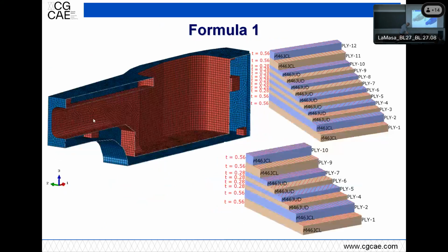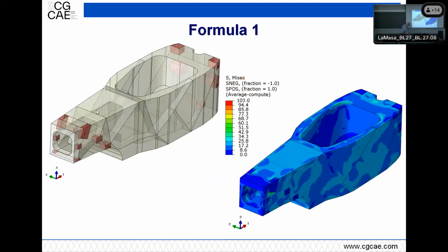And so I also tried a different approach. Following the suggestions from the topological optimizer, I said, why not have a boxed structure which can still be built with rapid prototyping, and place sheet metal more or less where the topological optimizer was telling me to place material, and then run a size optimization, so changing the thickness within a minimum and a maximum with continuity. And this is something that